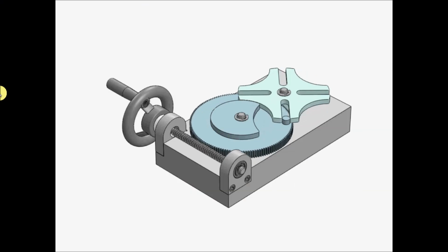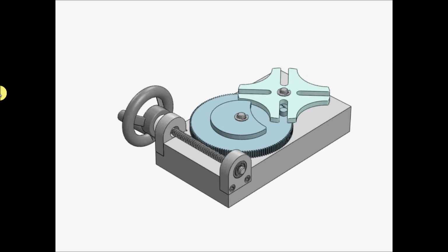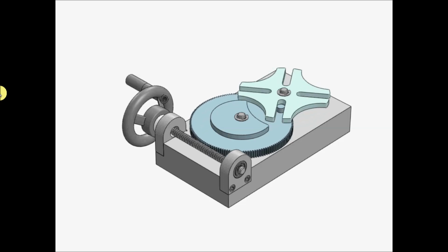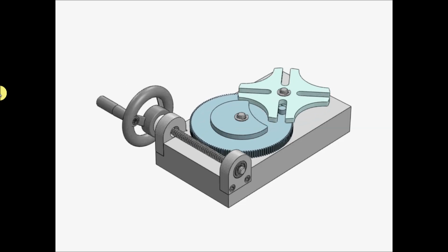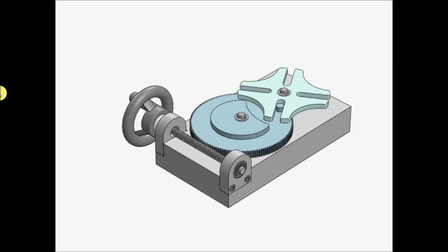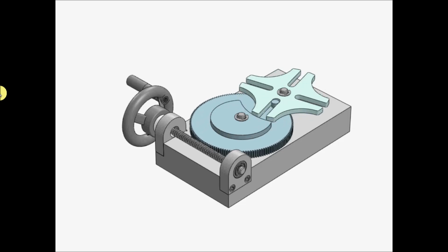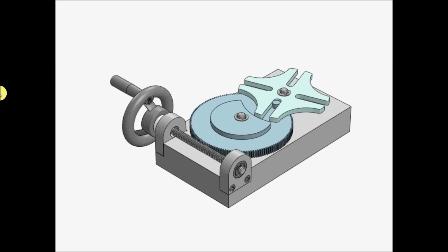So this Geneva cam is going to run like this, okay? This was one of the older ways of timing before robotics and motion controllers were invented. This is how they were able to maintain a delay in automation. Because think about it. In older ways of automation, all you had is a rotating motor.